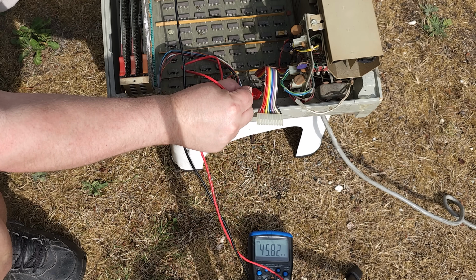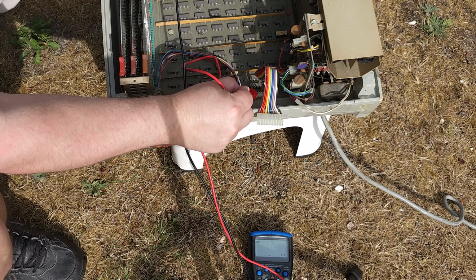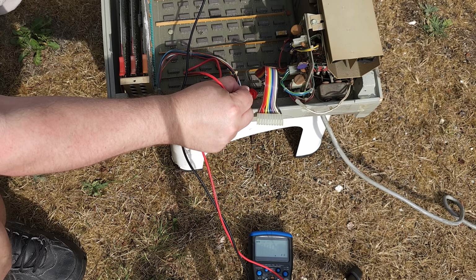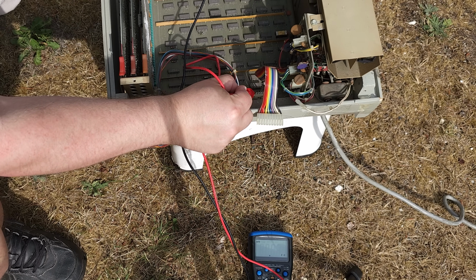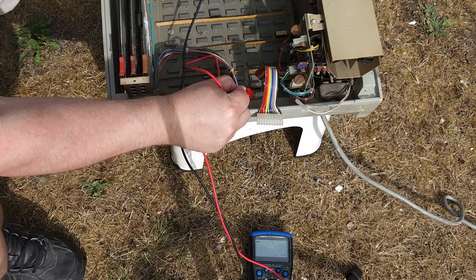The next thing I'm trying to do with my multimeter here is figure out which wires on this motherboard power connector are for which voltage rails by tracing things between known power pins on the ICs back to the power supply. This will hopefully aid me in determining if the power supply is putting out appropriate voltages, which will in turn determine whether I feel safe enough to try plugging in the motherboard.